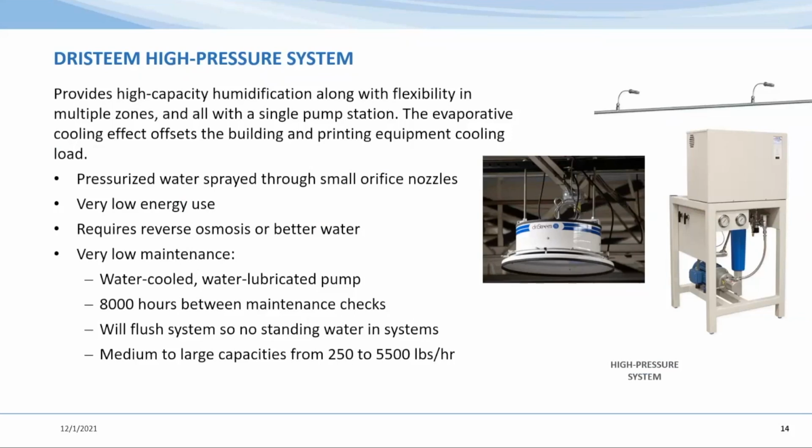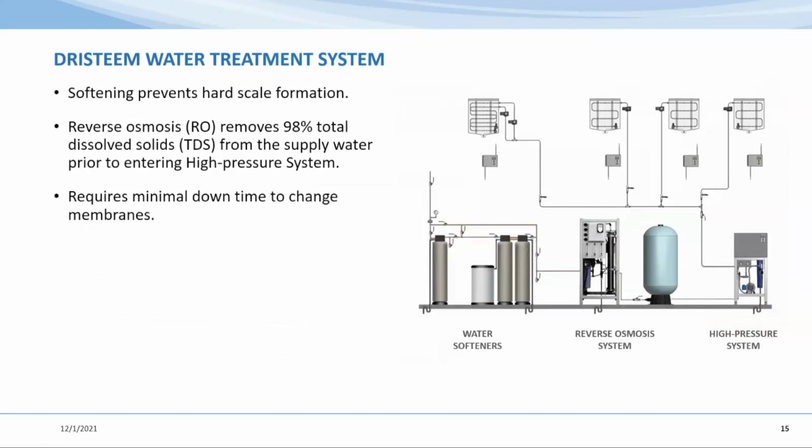The other great feature is low energy use to run this. It's a single horsepower pump along with energy for the fans and controls. It does require reverse osmosis water or better. And lastly, it is a lower maintenance technology as it's fed RO water and it's water lubricated, so 8,000 hours between maintenance checks, etc.